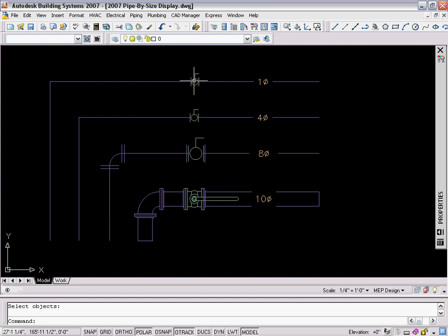You'll see that the graphical valve symbols scaled along with the annotations, but both the 1-line and 2-line representations for the MV parts did not scale, and that is because those don't scale. They will always stay their absolute size in the drawing itself, whereas the graphical size will scale accordingly along with this.